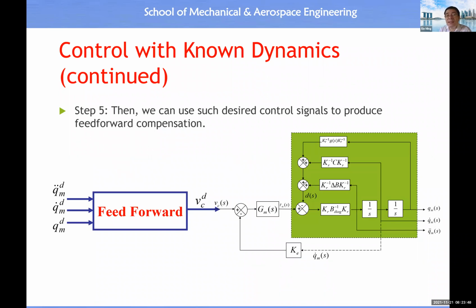Then you can make this expectation. You may expect that if we supply this value provided by the digital twin of your robot to the physical robot, then let the physical robot take this as an input. If everything is perfect, then your physical robot may produce a motion which will be exactly equal to the motion at the input side. Okay, so this gives us an advantage of achieving the control result in a single step of computation, because this computation can be undertaken in a fraction of a second.